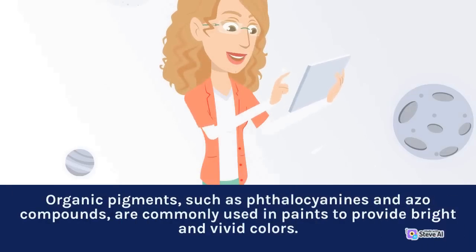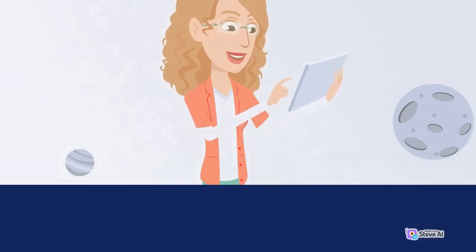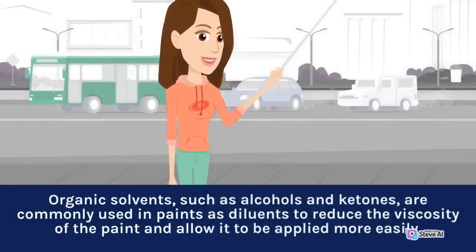Organic pigments, such as phthalocyanines and azo compounds, are commonly used in paints to provide bright and vivid colors. Organic solvents, such as alcohols and ketones, are commonly used in paints as diluents to reduce the viscosity of the paint and allow it to be applied more easily.